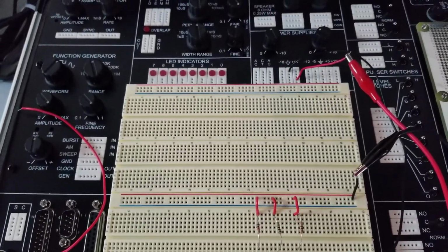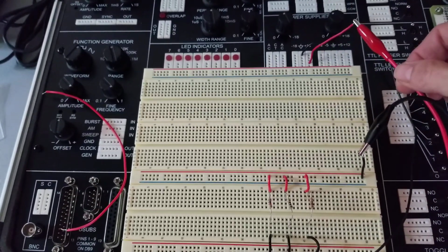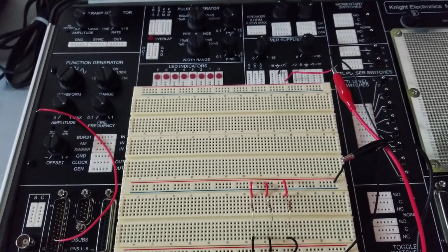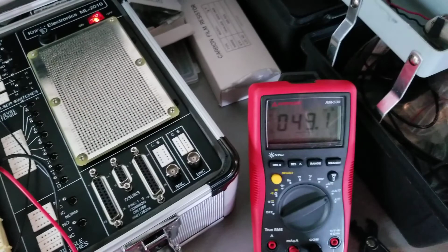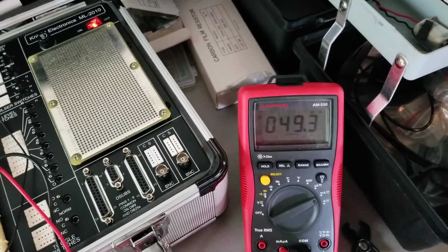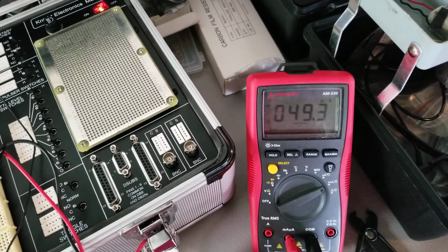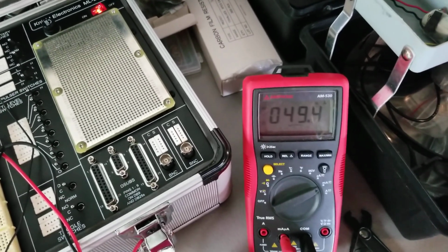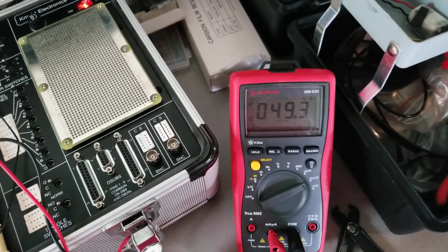Now, to measure my total current, I've actually made the break here where I connected the power supply in, and I put my red lead here where power was coming from, and ground down here where it was going to. I'll turn on my power, and there's 49.23 milliamps. Great, we're right on target. Any fluctuations like that are due to real life variables. Nothing's going to come out as calculated. If it does, take a picture and a video of it, because very rarely does it come out 100% perfect.